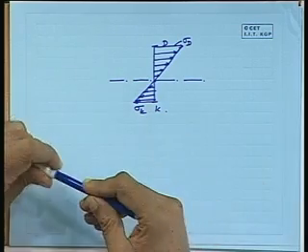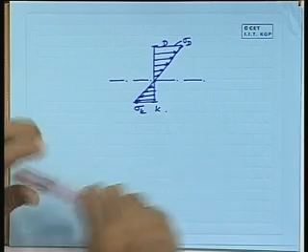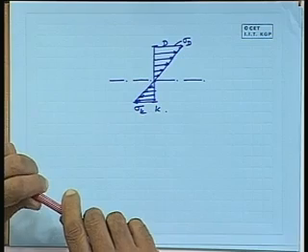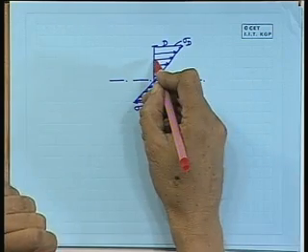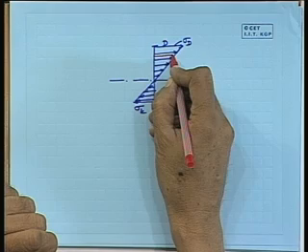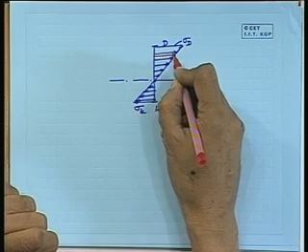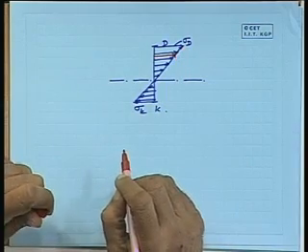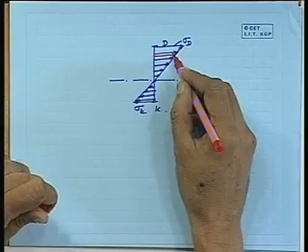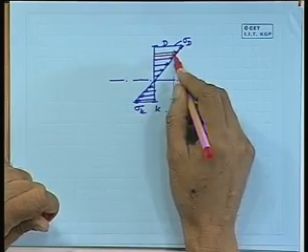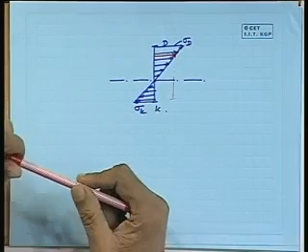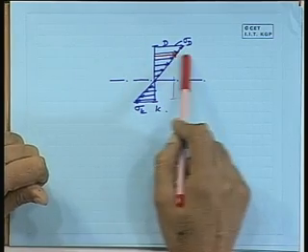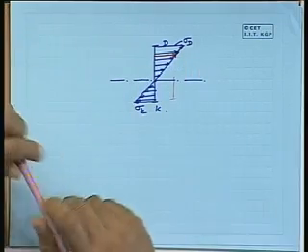Now many a time what happens is that it is not possible to have very thick plates, and this limiting stress which we consider may be up to here, and then we say that beyond this let us use high tensile steel. You can still use mild steel in the core, but where higher strength is required, you can go for high tensile steel. So from here one can say that the high tensile steel will have a higher limit.